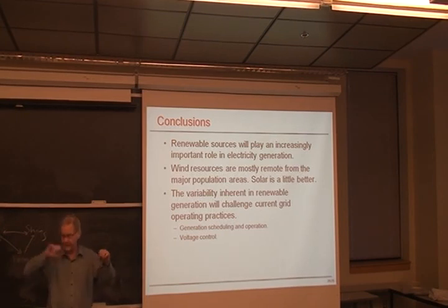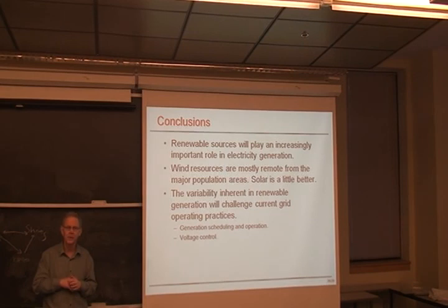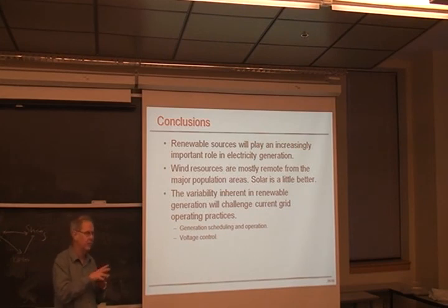At the next load bus along, you're holding the voltage solidly here, but they're seeing the voltage going up and down out there. With solar, you're sitting right at the load, so you're regulating the voltage at the point of the load as well. You don't have the voltage drop across the interconnection, so you don't have that issue.